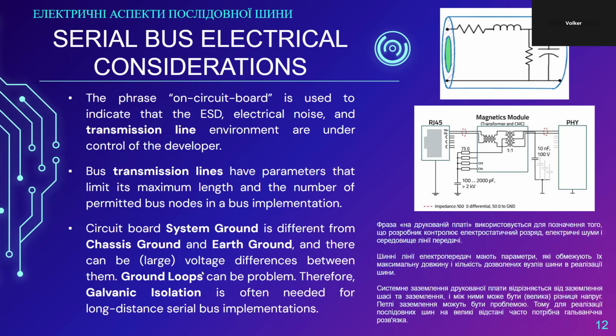Because the cables, or even the shield cables, are not ideal. They have an ohmic resistance, even if it's just a few ohms. So suddenly you're creating a voltage drop, and that voltage drop can affect your signal. That's the danger with ground loops.